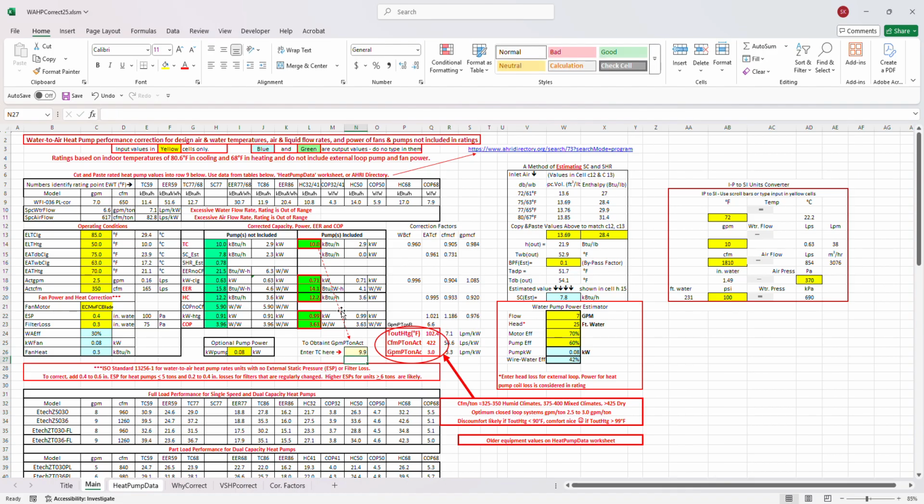This is still a little high. You see we have a high sensible heat ratio. Now, this is bad, especially at part load, because at part load you've got to have more dehumidification. So what we're going to have to do is let's try to go down to 300 CFM to get that down. 70. We've got nice hot air, and we got 0.74. So we're pretty well equal.